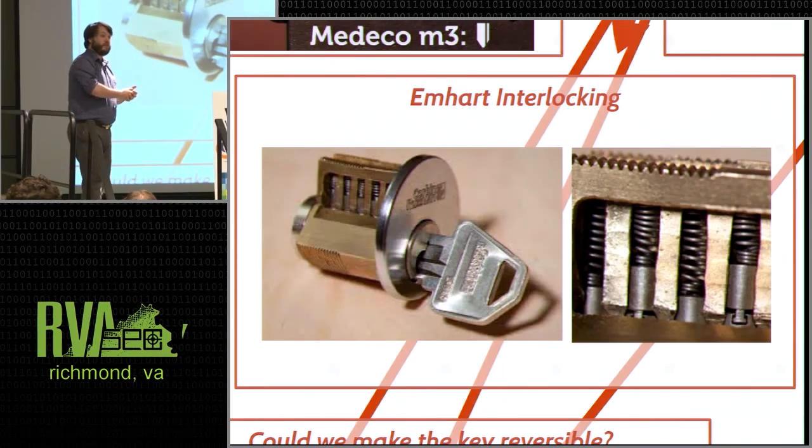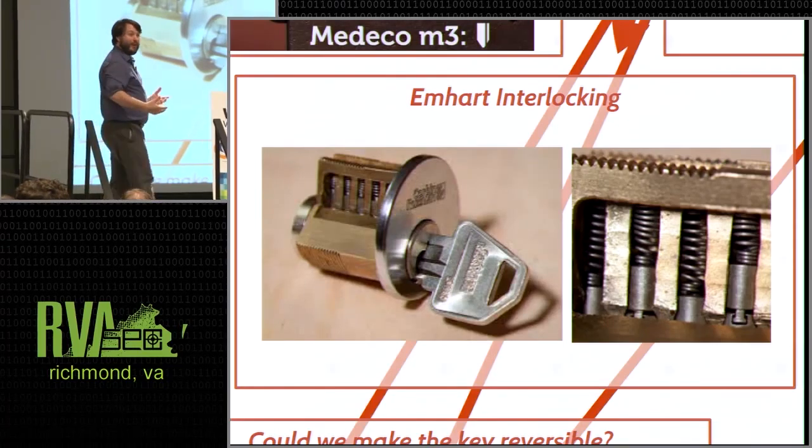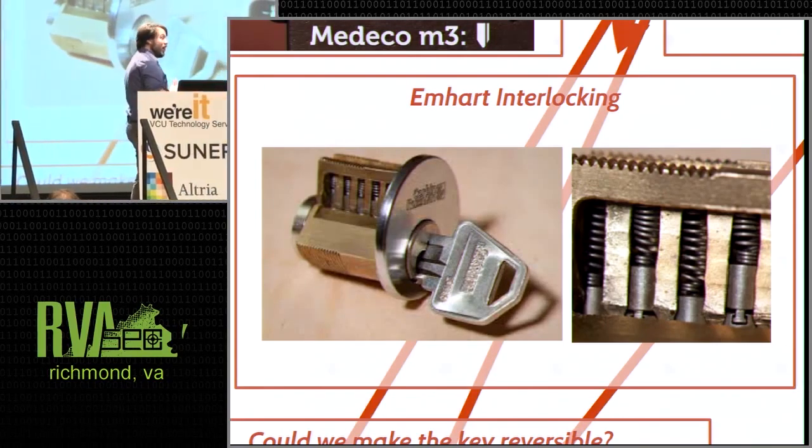When the key is fully inserted into the lock, the pins can rotate far enough that all of the joints are facing outward, and they'll all be sitting at the shear line. The plug has channels cut into it that the bottom of the driver pins can rest in, so they stay in alignment, so they can be recoupled when you turn it back around to the locked position, and they can separate from one another. This is a really cool lock.